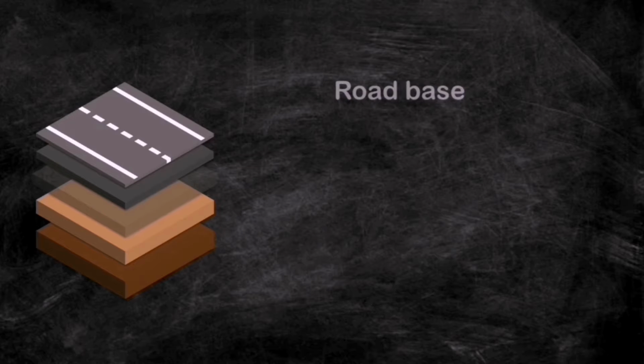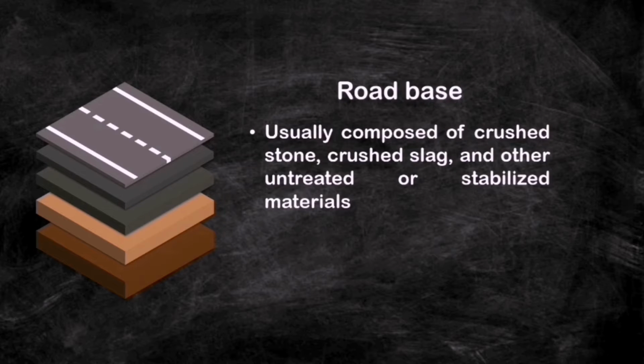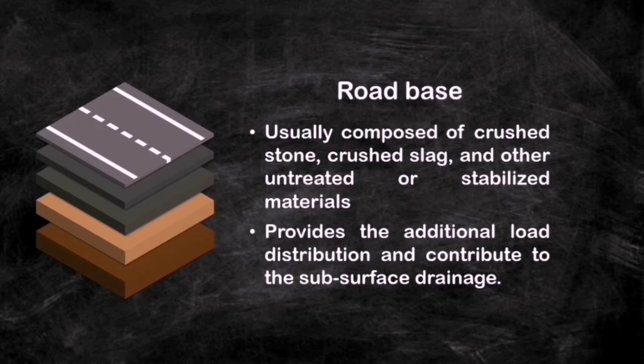The third layer is road base. Road base is usually composed of crushed stone, crushed sand, and other untreated or stabilized materials. It has to provide additional load distribution and contribute to the subsurface drainage.